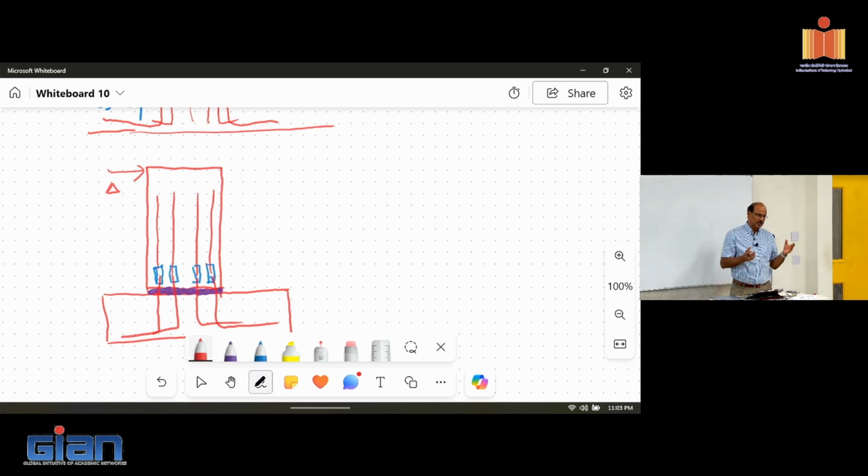So this is basically what we have been talking about as an emulation. We are emulating the rigid connection that cast in place uses. We couldn't use the continuous reinforcement, but instead we are introducing some form of couplers or sleeves to establish the full continuity so that I can create that behavior similar to the cast in place wall.